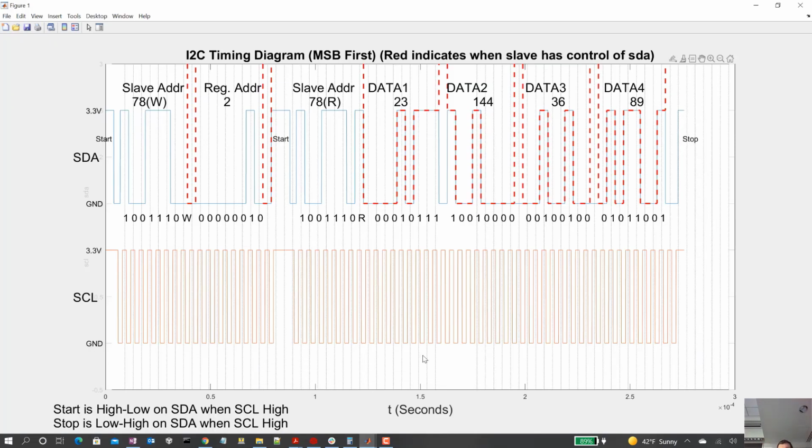protocols, right? We've looked at this a bunch of times, but this is kind of what we're going to see if we can find this kind of protocol in the data sheet. I told you guys that a lot of chips that I've used at least go along this protocol where you first send over the slave address of the slave you want to talk to. The master does this, and then you are telling the slave what address inside the slave chip you want to read from or write to.